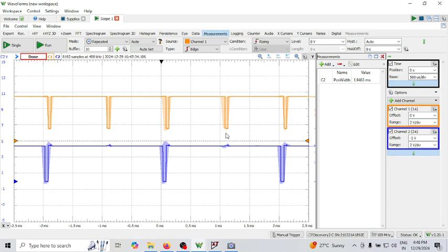So before that you are giving one more trigger signal. Since the capacitor voltage has not yet reached VTH, this is not considered a valid trigger signal. You can see now this is coming down here. So at this point your capacitor has reached VTH. Now it goes to the stable state and you are giving one more trigger signal here. The moment you give the trigger signal, it's coming up now.